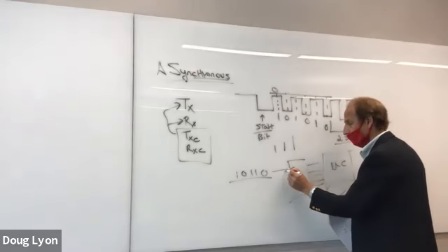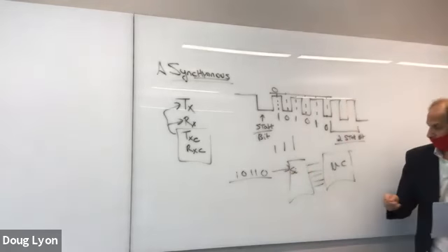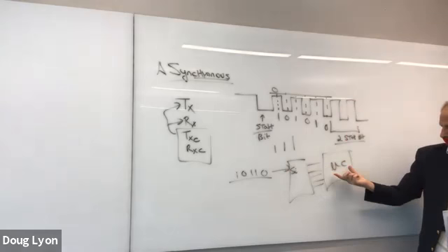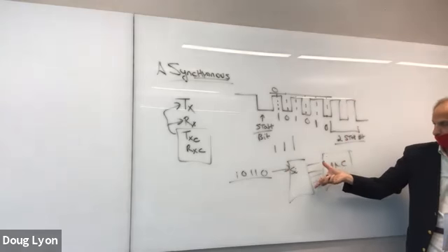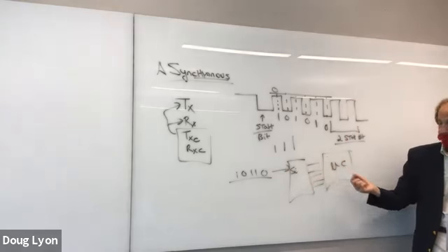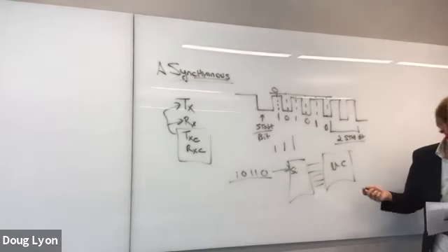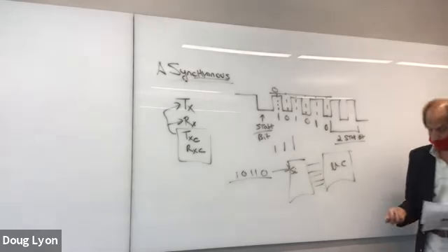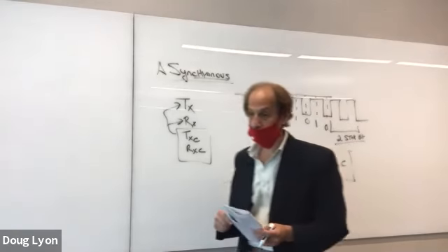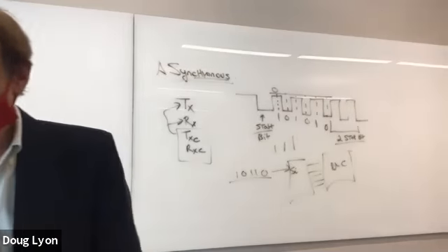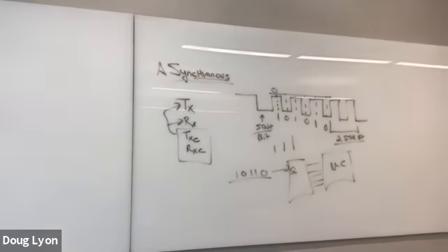So this goes in marching along 1 bit at a time. So it comes out in parallel, and the microcontroller is signaled that these bits are ready, and it takes those bits and pushes them into a stack or throws them into an array, or does whatever it's doing with serial data. And you see this all the time when you open up the serial monitor on your Arduino IDE. Right, that's a critical task.